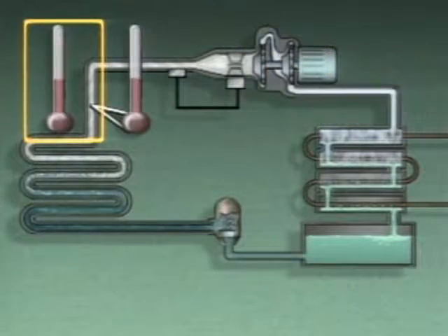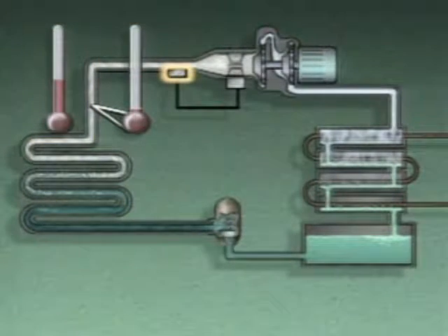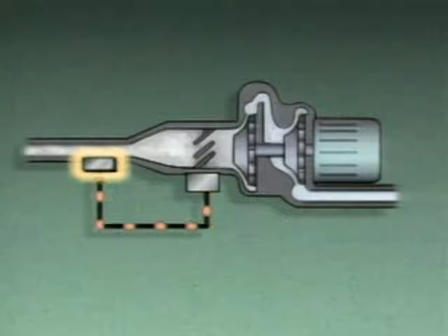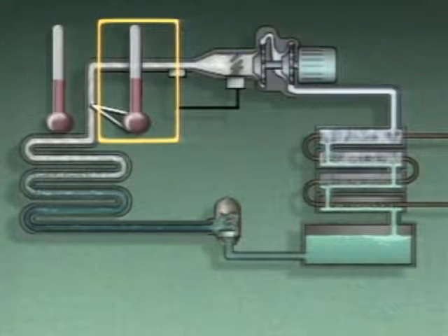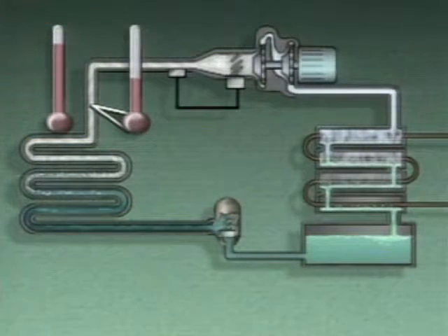Another way that refrigerant flow can be controlled in refrigeration systems that have centrifugal compressors is by using dampers or vanes. These devices are often located in the compressor suction line. When the temperature of the substance being cooled is too low, the temperature of the refrigerant flowing to the compressor drops. The dropping temperature is sensed by a temperature sensor, which sends a signal to close the vanes slightly. This reduces the amount of refrigerant that enters the compressor, so the flow of refrigerant decreases. The reduction in flow will cause the refrigerant in the evaporator to be warmer. This causes the temperature of the substance around the evaporator to increase back to its desired value.